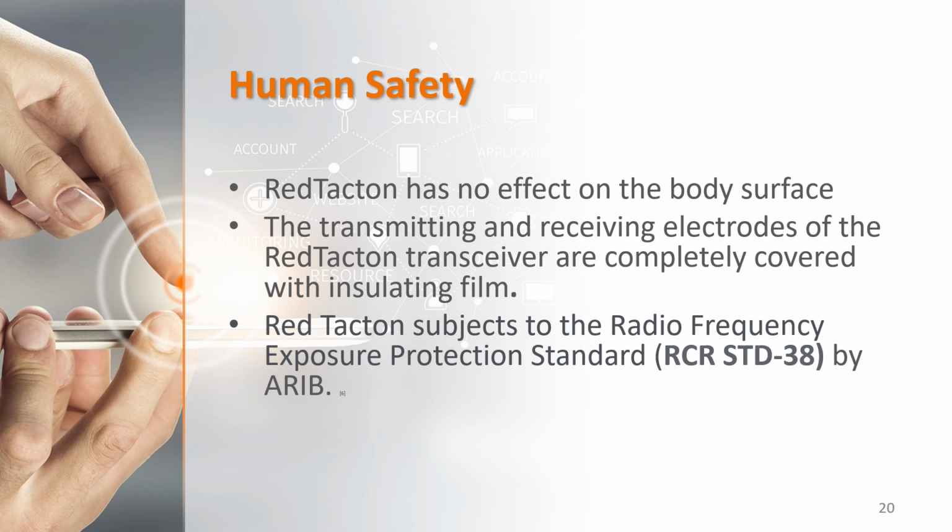We will further discuss human safety. The transmitting and receiving electrodes are completely covered with insulating film, so the body of the person acting as the transmission medium is completely insulated. This makes it impossible for current to flow into a person's body from the transceiver and does not harm the person's body. When communication occurs, displacement current is generated by the electrons in the body because the body is refracting minute electric fields. However, such displacement currents are very common everyday occurrences to which we are all exposed. RedTacton conforms to the Radio Frequency Exposure Protection Standard issued by the Association of Radio Industries and Businesses.